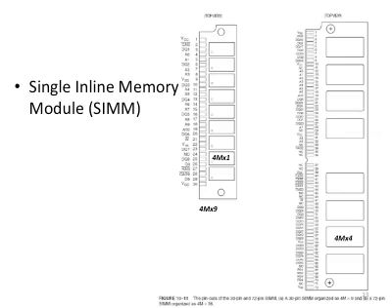As we have very high density on the DRAM chips, if you want to build out a memory subsystem, oftentimes you need to employ multiple DRAM chips. For example, here we're showing a so-called single inline memory module, or SIMM. On this PCB board, we have 9 DRAM chips, and each of them is a 4 meg by 1.